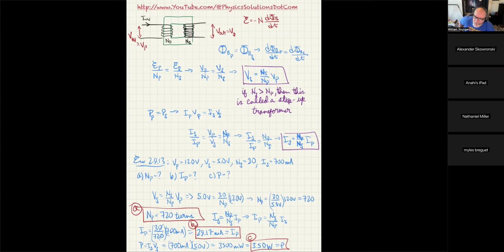We use the formula for the magnetic flux, phi equals the integral of B dot dA, to calculate the flux through that coaxial cable. And then we use L equals phi, the magnetic flux, divided by I, the current, and that gives us the capacitance, or excuse me, the inductance in henries.